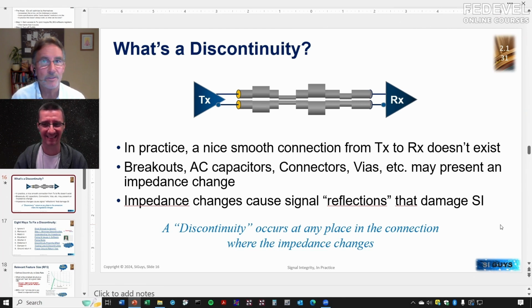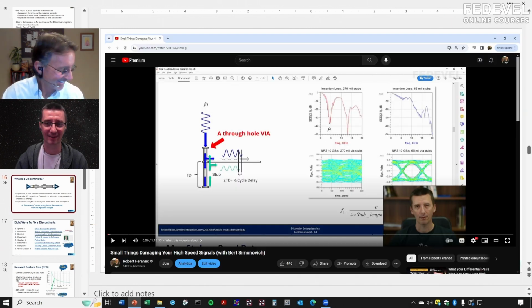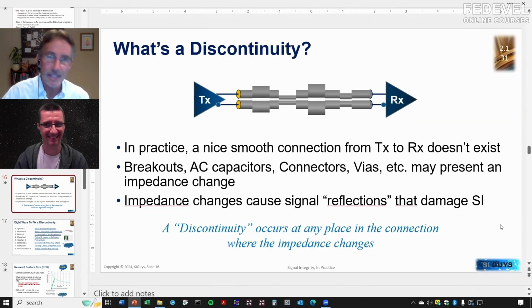It might be the weave of the dielectric, it might be the etching process, it might just be a poor manufacturing process. I've done some videos on this topic, so if someone would like to know more about where the losses and imperfections in PCBs are, they can watch the other video. Good, I hope you'll link that so people have what they need there.